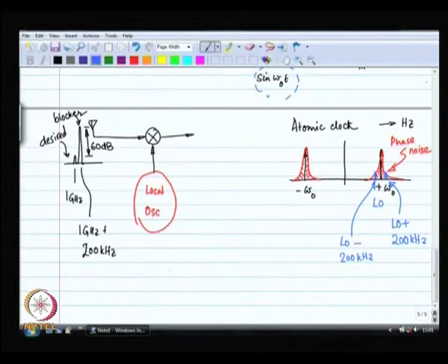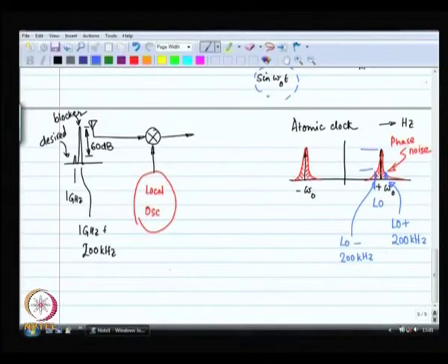So, that something is going to multiply with my blocker signal, right, and the resulting product is going to come on top of my desired signal at the output. So, that means that this separation has to be 60 dB, more than 60 dB.